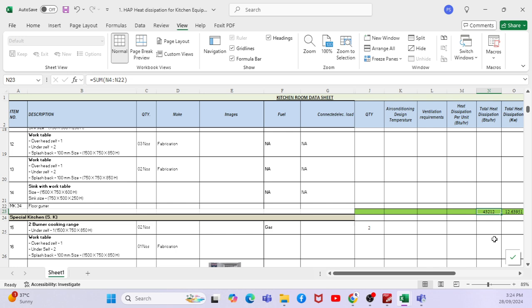But I have a question here. For example, you've shown an example where you have a kettle. In kettles, we know that after a certain point you'll have steam generated from hot water. Basically, that is not a sensible load, right? It is a latent load. So my question is, is that not accounted for in this data sheet, or how do we consider that in the heat loads, or do we just reject that particular load?